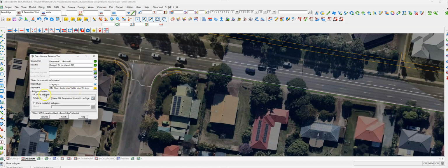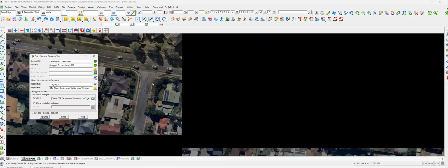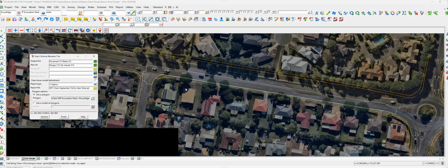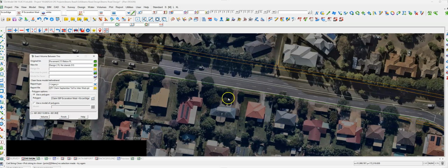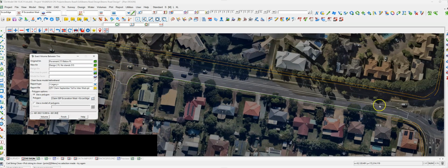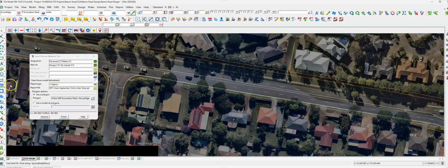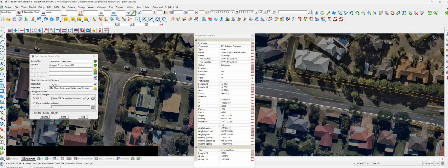Yep. You could do another report here if you wanted to. I'm just going to put both numbers in the same report. Good. And we've got our second quantity. So 661.902, and that's it. That's as difficult as quantities are in 12D to run. You could solid hatch this. Some tool here called CAD fill. You can solid hatch that, which we might for this instance, just as an example.